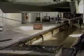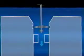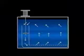One of the most common quench systems is the open tank. Properly designed open tank systems will employ either a pump, impeller, or spray agitation, or a combination of all three if optimal quench uniformity is to be achieved. Of these, the most common agitation is impeller agitation. There are numerous designs possible, which depends on the configuration of the load being quenched, size and depth of the tank, the quenchant being used, and other factors.